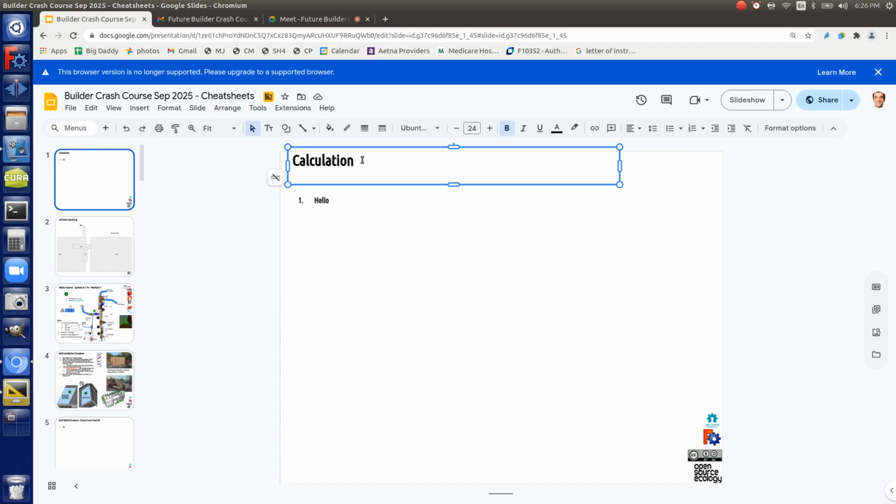How the wood is arranged also determines what kind of strength you get. Think about the joists. We put them on edge, right? That's because they have more meat.